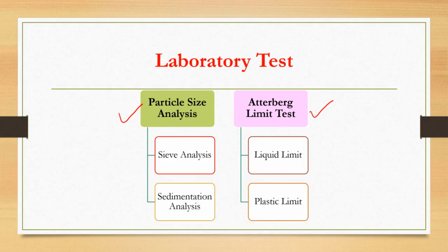For particle size analysis, we have two types of testing to be carried out at the lab, which are sieve analysis and sedimentation analysis. On the other hand, for the limit test, you need to carry out two tests also, which are liquid limit and plastic limit.